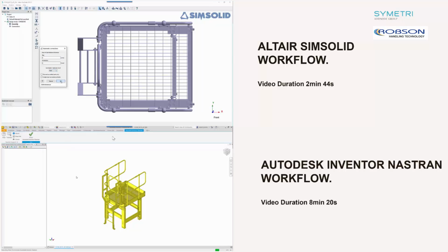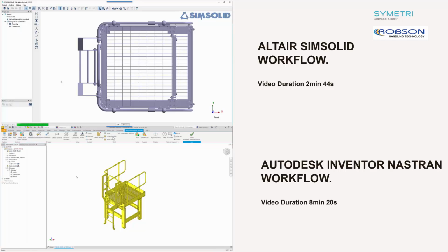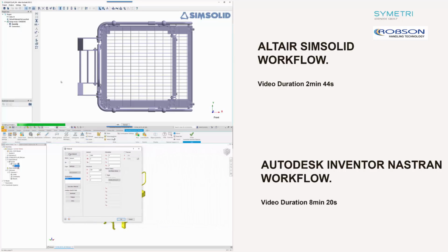SimSolid tends to import the model as a whole. It recognizes your bolted connections, so you don't have to get rid of any of that geometry that you've already created. So your geometry complexity can be brought in as well. It reads the files, evaluates the connections, and gives you a summary or automatically assigns what contacts need to be made. Here within Nastran, we're currently just assigning the material.